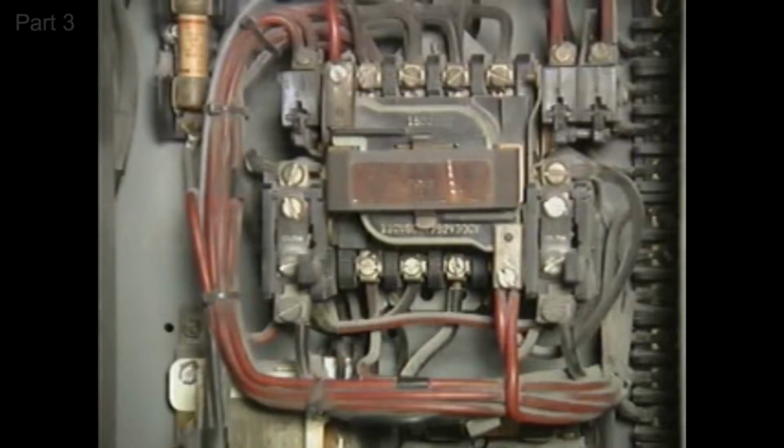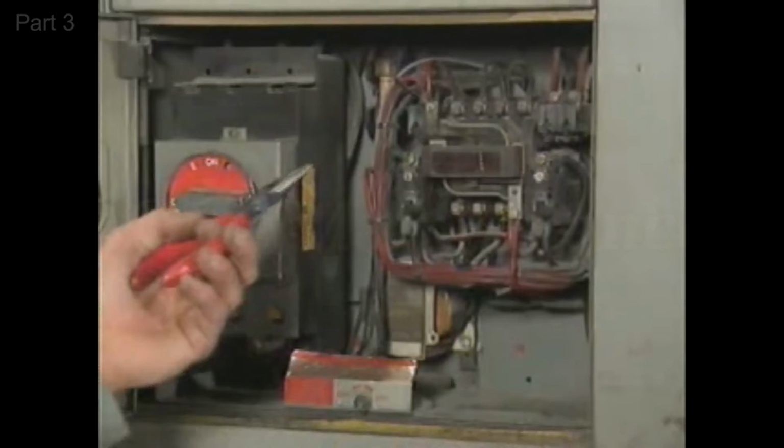If the visual inspection does not result in finding the cause of the problem, the next step, generally, is to take electrical test measurements. Three common faults you can test for are grounds, opens, and shorts. Test procedures for each of these problems are covered in some detail in this unit in the topic called Troubleshooting.